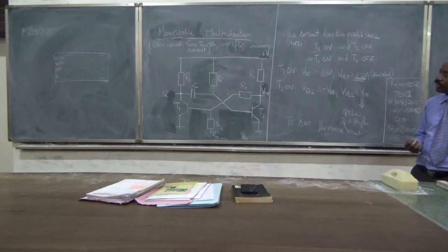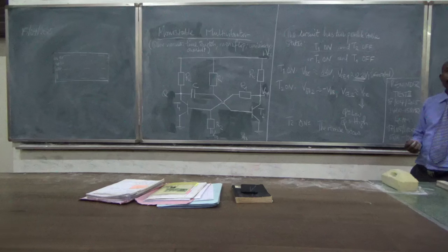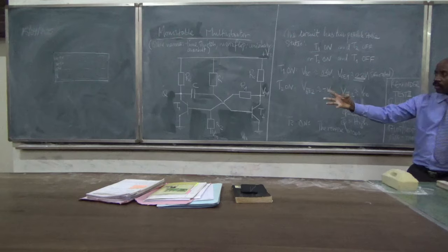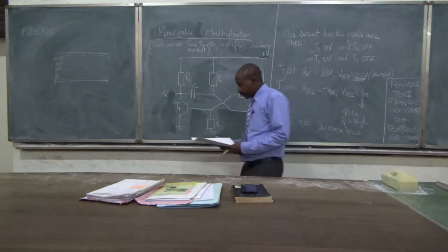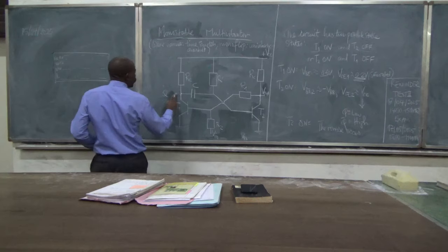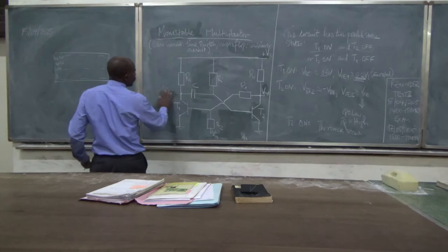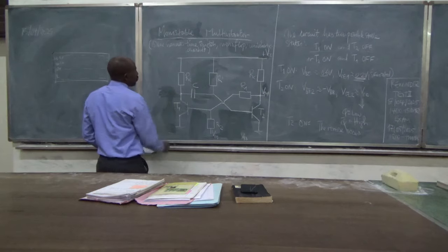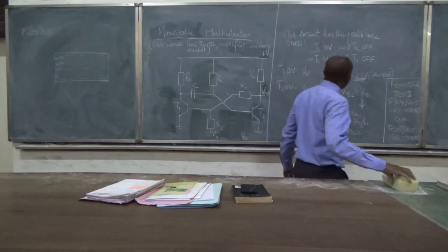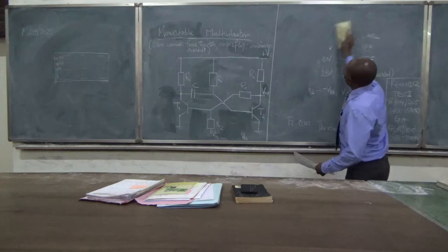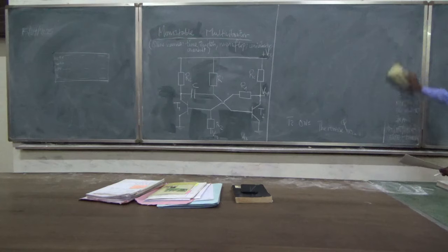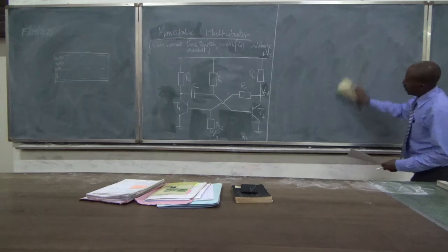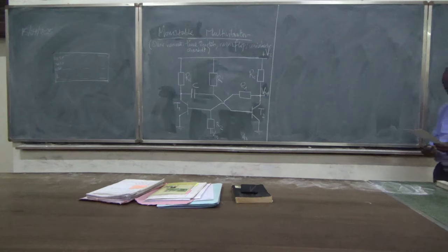And that's where I normally give an example of the traffic lights, whereby you have this one lighting, the other one off. This one lights, the other one is off. But here we are not having this state, we are only having the output there. And that's why we call it a one shot, or a monovibrator, a monoflop, has one flop, as other names.